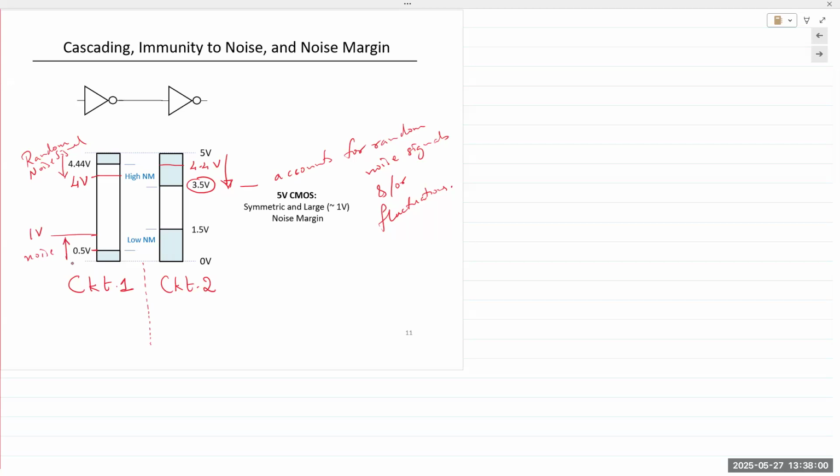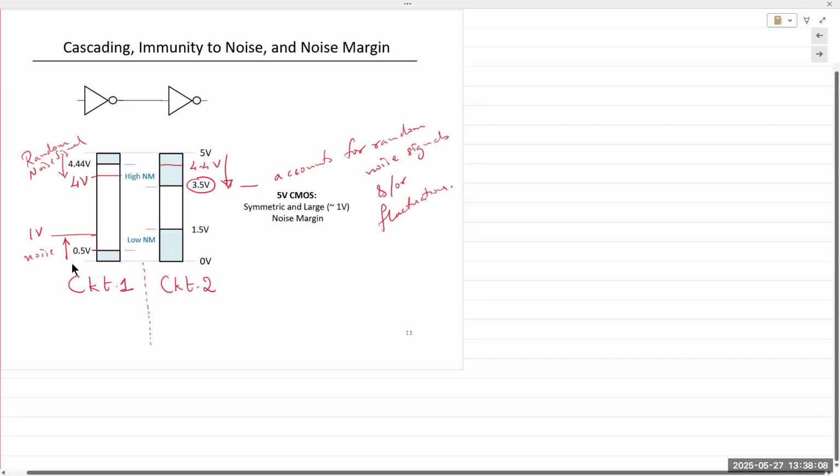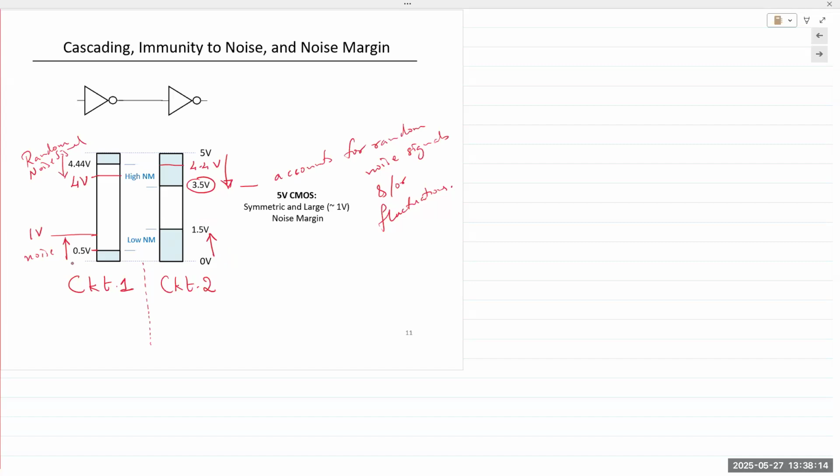And that 1 volt, instead of being recognized as 0, may be recognized as 1 or may be recognized as undetermined. And if that happens, then of course, obviously the circuit's not working. So there's a tolerance built in. Instead of 1 volt or 0.5 volts, it's all the way up to 1.5 volts. Hence, input sides always have a wider range of tolerances for voltages, whereas the output is far less. Does that make sense?